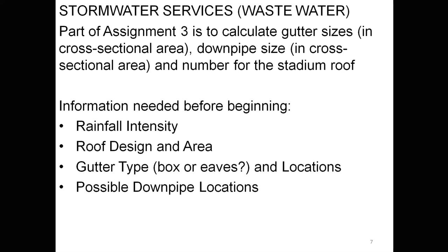Okay, so if you've got an upside down pyramid held up on one column, then obviously what you're going to need is a downpipe that goes through that column so that any water that's collected in there will actually be able to get out. Okay, so in that example, of course you won't have a gutter, you will just have a downpipe. Okay, so really what we're now going to do is to figure out how to determine those things, because they can be seen in isolation as well.